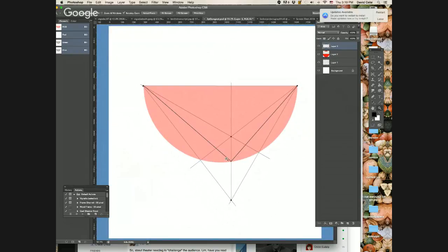And this is important because we want basically a square in plan, or a right angle in plan, so that we can find the diagonal vanishing point. So the diagonal vanishing point will be at 45 degrees of that 90-degree angle on the horizon.